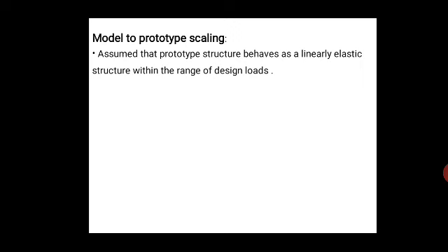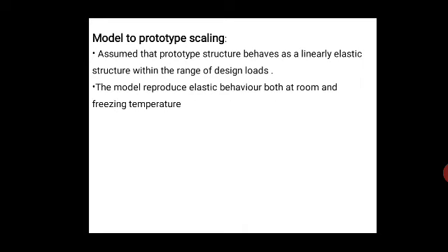And here in this prototype structure, the behavior of the structure is assumed as linearly elastic within the range of the design loads. So the photoelasticity model reproduces elastic behavior both at room temperature as well as stress freezing temperatures. See, this stress freezing temperature and stress freezing technique we will be discussing in the next module, that is three-dimensional analysis of the three-dimensional photoelasticity model.